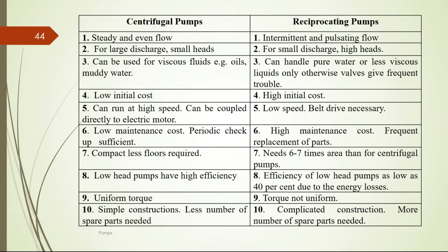Centrifugal pumps have low maintenance cost, where periodic checkup is sufficient, whereas reciprocating pumps have high maintenance cost and frequent replacement of parts is involved. Centrifugal pumps are compact and require less floor area, whereas reciprocating pumps need 6 to 7 times more area than centrifugal pumps.